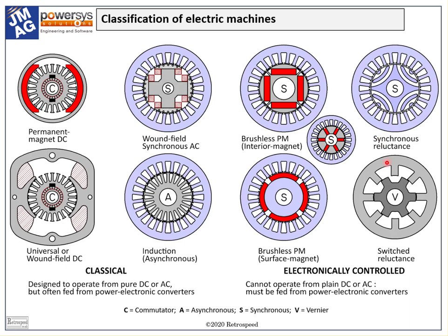Lastly, we must include the switched reluctance machine. This is not an AC machine. It operates with a series of unidirectional DC current pulses, which are synchronized with the passage of the rotor poles past the stator poles, which are usually wound with 3 or 4 phases. This requires a power electronic converter circuit which differs from that of the standard AC inverter. It also requires its own control theory because the principle of field orientation does not apply.